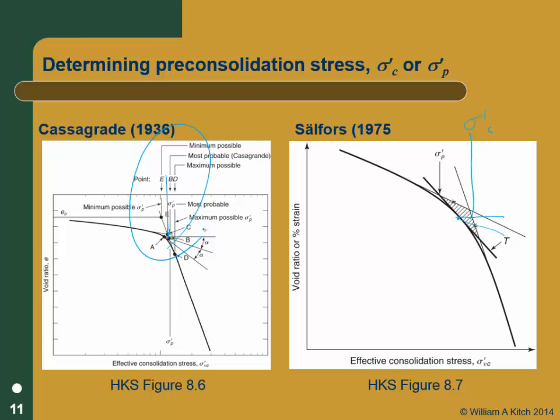But what's the real problem? The real problem is you don't have a good sample. If you've got a highly disturbed sample, you should just give up on trying to get it returned to the field condition and go out and get a good sample.